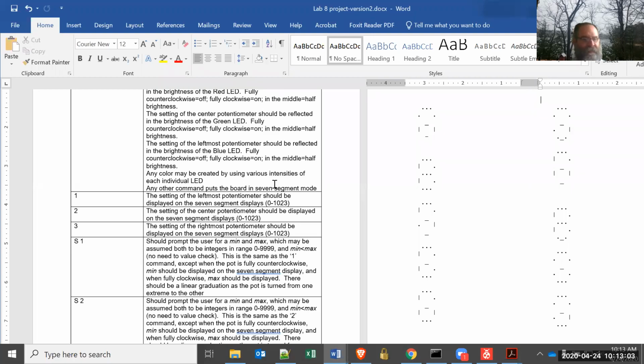If you've dabbled in old style BASIC, there is an inkey call that returns a null if there are no keys waiting in the buffer. You need some routine to see if there's any keystroke in the buffer, and if not, read your potentiometers, update the OCR values, and continue on.